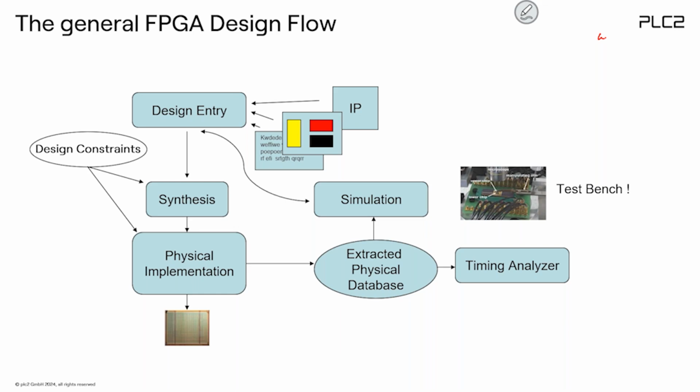If you look at the FPGA design flow, the CDC and the solution for it, the designing of CDC structures, happens right here. You are responsible for this during the design engine. This cannot be done automatically by the synthesis or by the physical implementation. No, you have to do it.